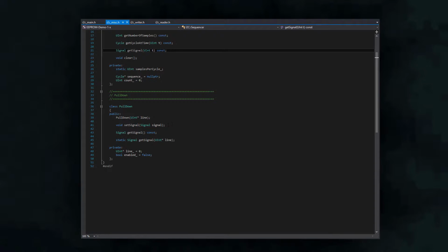Now the pulldown class is, as the name suggests, an interface to the data lines and clock lines, because the way I have designed the framework is that I did not want to have access to the actual GPIO pins or the C functions that control the GPIO pins. So instead of controlling them directly, I'm going to use a simple integer or a pointer to an integer, and different nodes on the bus are going to have the same pointer.